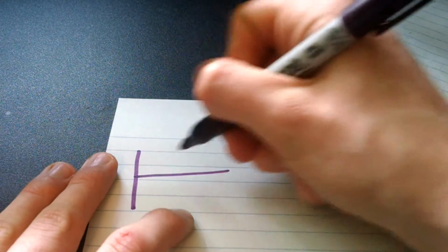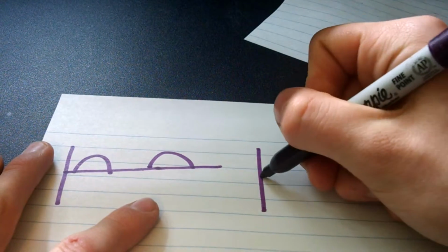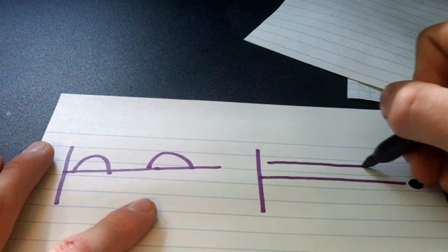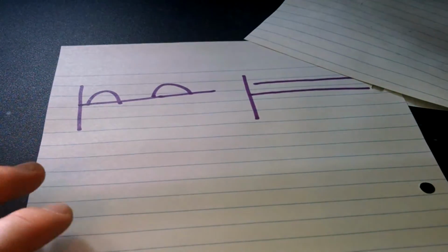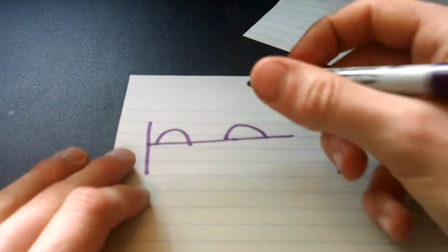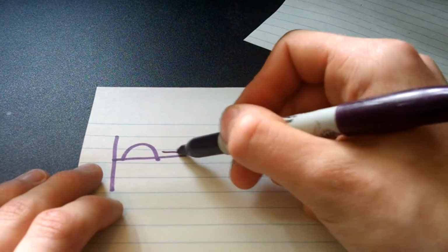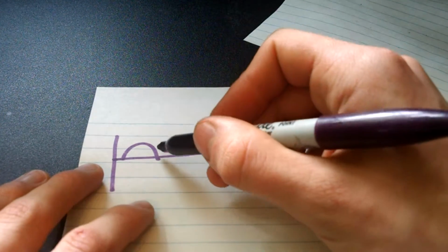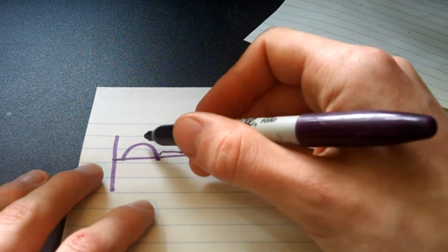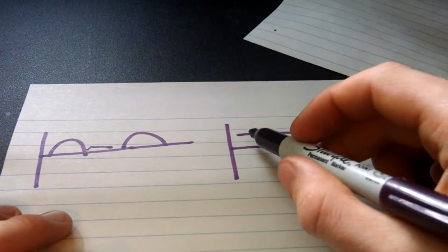So what a capacitor does is it takes this half-wave DC and turns it into smooth DC. This kind of capacitor is called a smoothing capacitor. And how this works is, when we have this, it goes into the capacitor and charges it up. So the capacitor is fully charged. But when we have this drop off here where there's no current, the capacitor actually releases some of the current to compensate for the lack of current or the imbalance. So it's constantly charging and discharging at 60 cycles per second, producing a smooth signal.